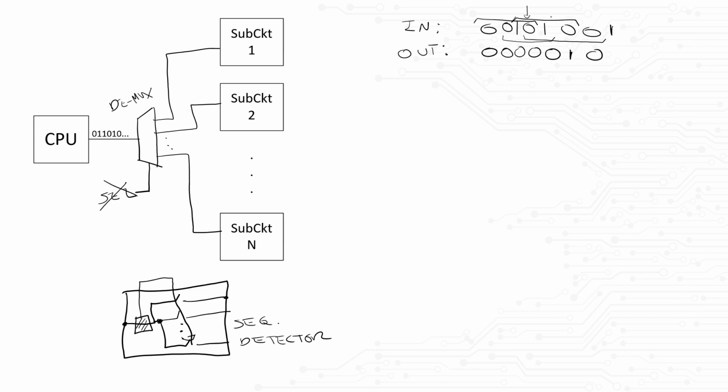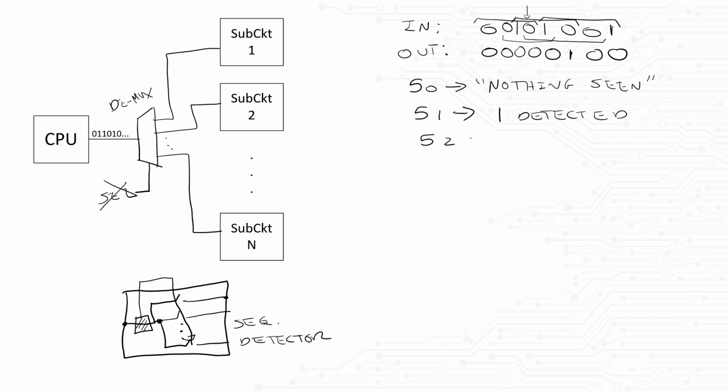If you are, you can follow up with, now that I know what my output should look like for a given input stream, then we should assign states. Since we are detecting 4 bits, we will need 4 states. Let's call S0 the nothing seen state, to give a little bit more intuition to what the state means. Let's also call S1 the state where we detected a 1, S2 the state where we detected a 1, 0, and finally S3 the state where we detected a 1, 0, 1.